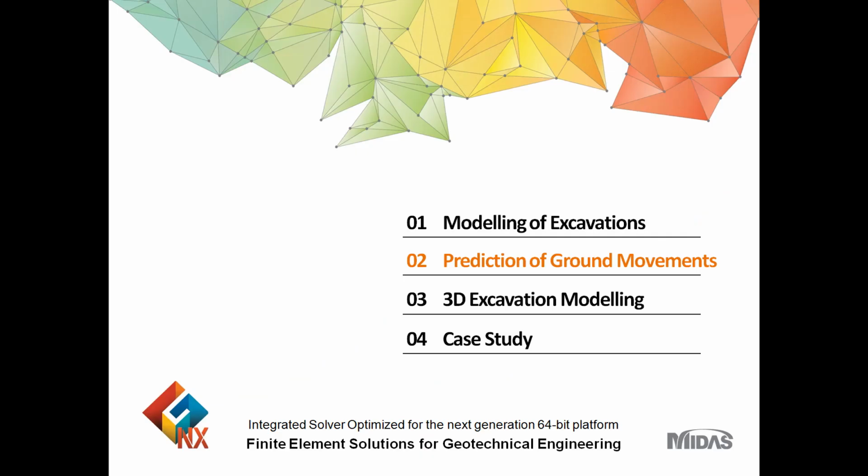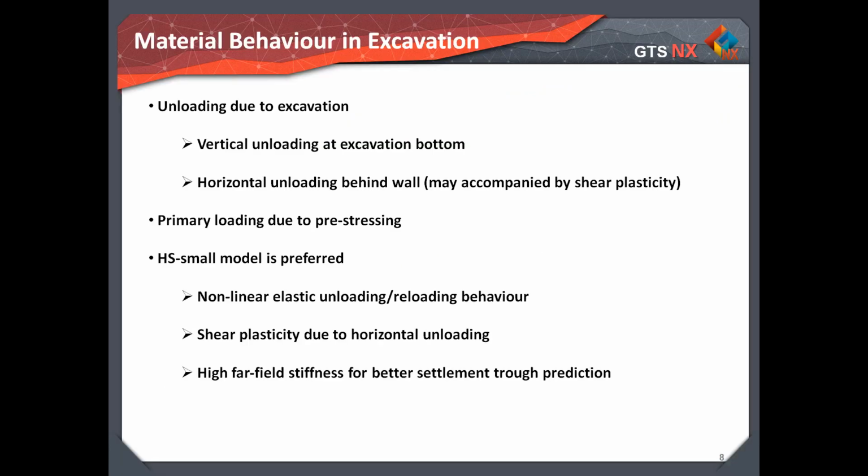Now I will overview the prediction of ground movements. It is now well recognized that in order to satisfactorily predict wall and ground movements resulting from deep basement excavations, a constitutive model which assumes linear elasticity should not be used.